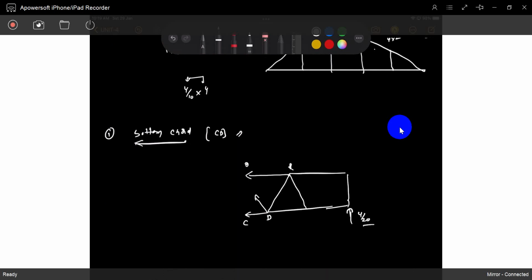So we want CD. How do we choose? We choose Q because of the unbalanced moment for the top chord and bottom chord. We choose a method where we balance the unbalanced moment. So we choose Q. RQ and DQ meet at the joint Q, so there is no perpendicular distance. There is no moment created by those two forces because they pass through the joint. So only you will get this H C.